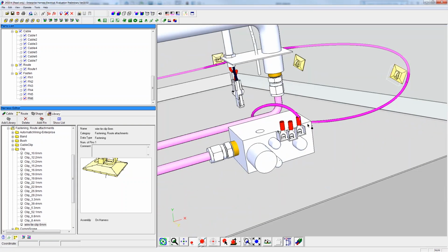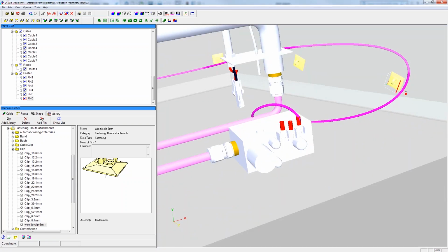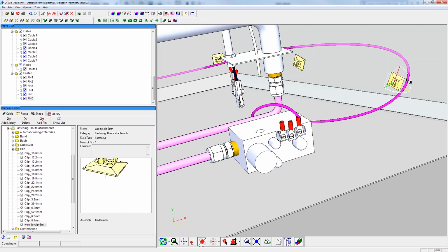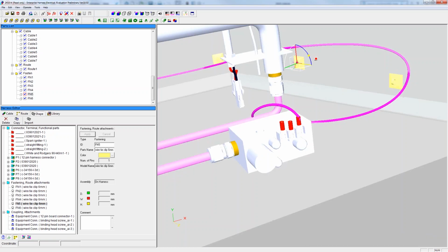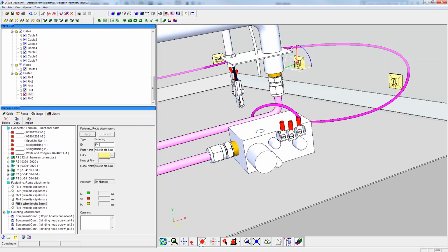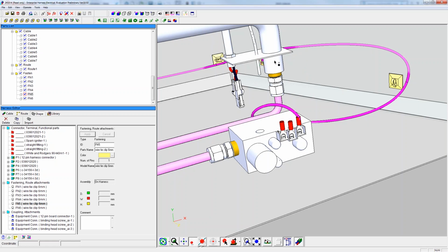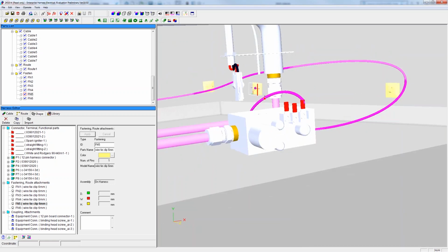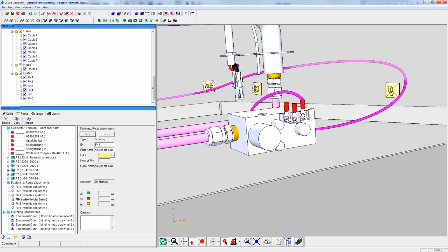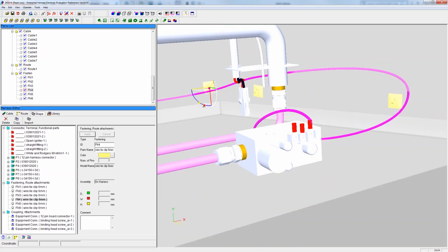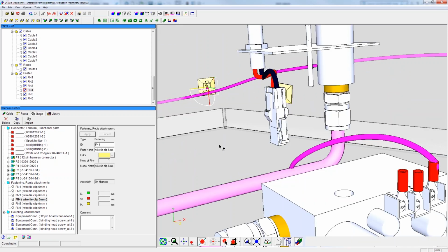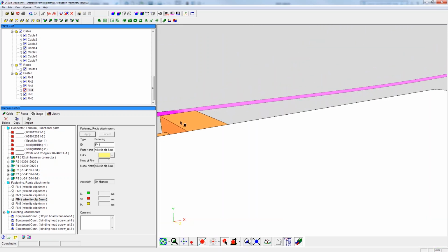So it's just put these in a default orientation. I can push and pull them around, maybe a little rotation here. Real life, I'd probably take more care on getting it exactly right, but just to move quick, I'm just going to put these in approximately the right spot. This one here is 90 degrees off. A little trick here, if I press the shift key, it'll snap that 90 degrees in one jump.